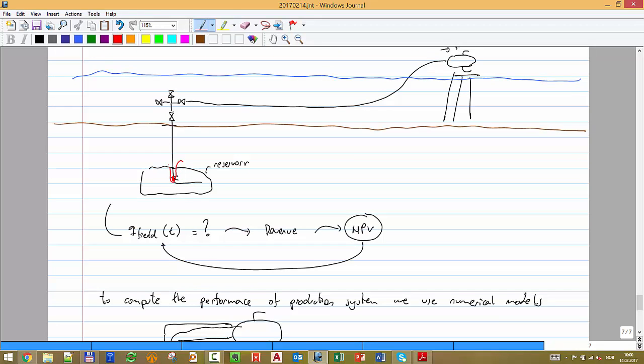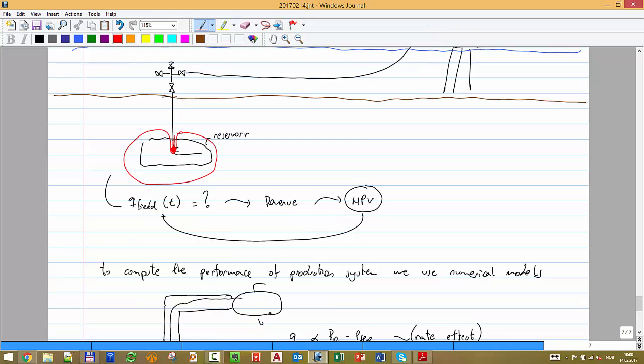What we are discussing now is only that part. That pressure is supposed to represent the minimum pressure that you have to have at that point to flow all the way to the surface. That's a very critical number, and it's not easy to calculate. If you have at least that pressure, you will be able to flow through the whole system all the way to the separator. You are physically able to flow.